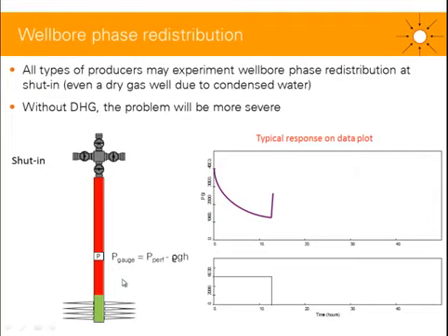So when we perform the shut-in, what might happen is the liquid droplets might fall down the wellbore. It might accumulate at the bottom of the well and in some occasions form a liquid-gas interface. As more and more liquid droplets fall down the well, this gas-liquid interface might move up. And if this is the case, then the fluid below the gauge is getting heavier and heavier. Density is getting larger and larger, and what we may tend to see on the pressure at the gauge is a stabilization, or even on some occasions a decrease in pressure, like I've shown you here in this example.